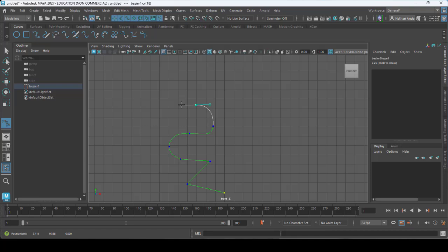It doesn't do it that way. What it does is you make that curve and then you can double back. You can select the curves that you have created and press Control, and that will let you break the tangent and make that into a Bezier corner. I'm going to press Enter, and that's going to finalize my curve here.